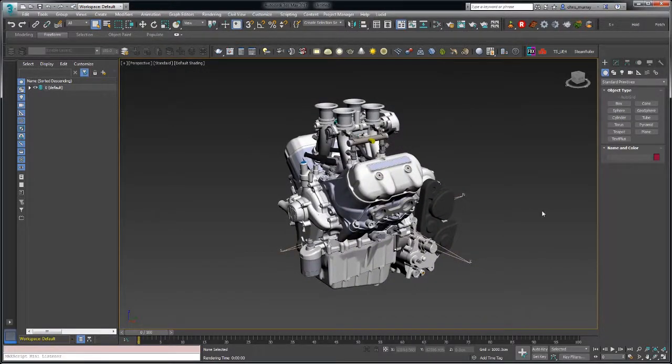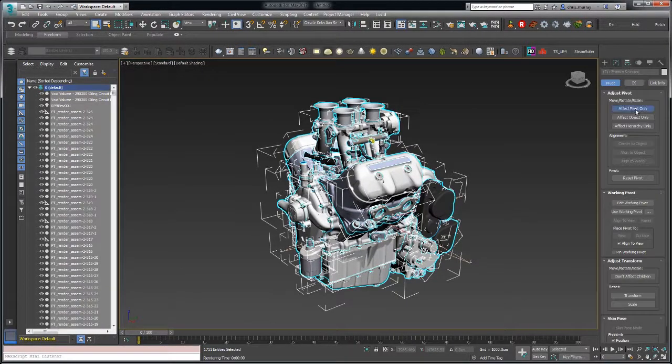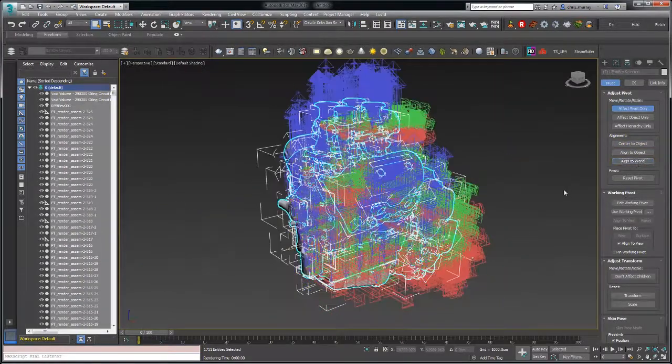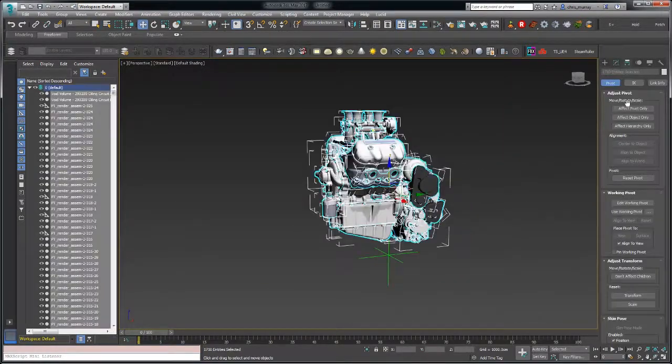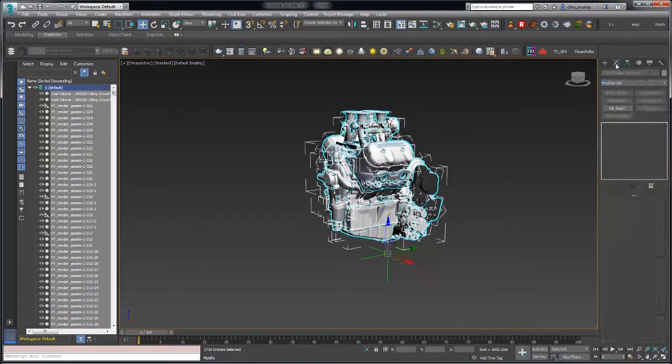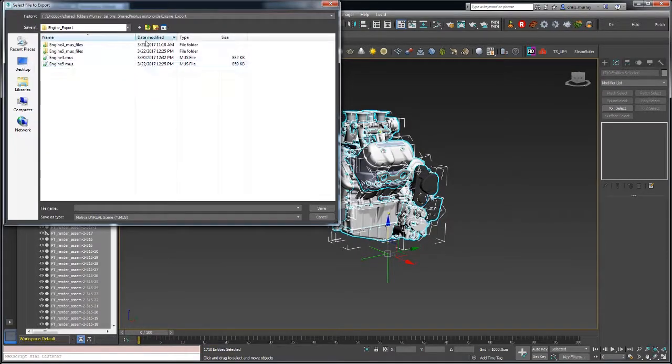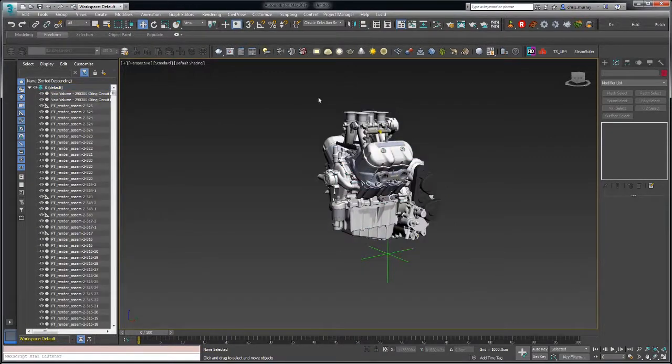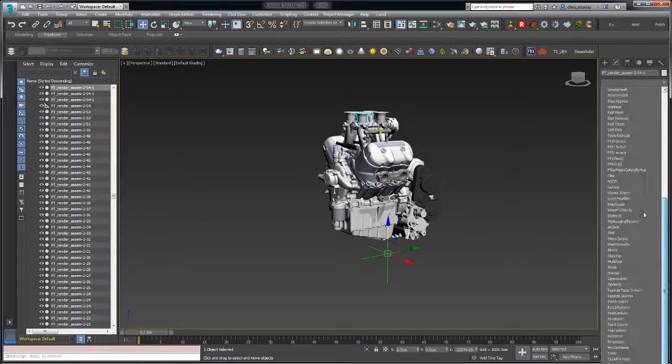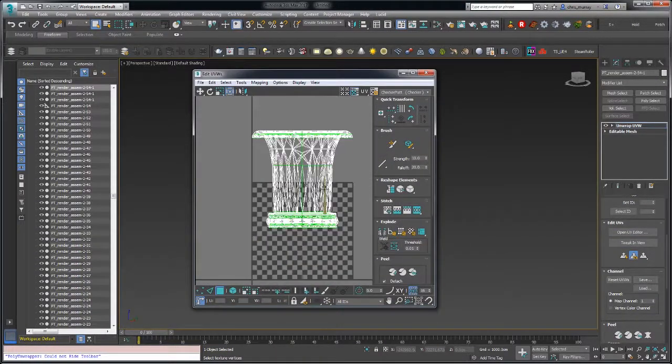Now we have to do a little bit of scene prep. So what we'll do is, again, 1,500 parts. Those are all of the pivot points for all of those parts. We need to centralize and localize those pivot points, and so we do that. And this is all a manual process currently in Max. Wink, wink. And you can see where we are recognizing opportunities for us to improve your workflow.